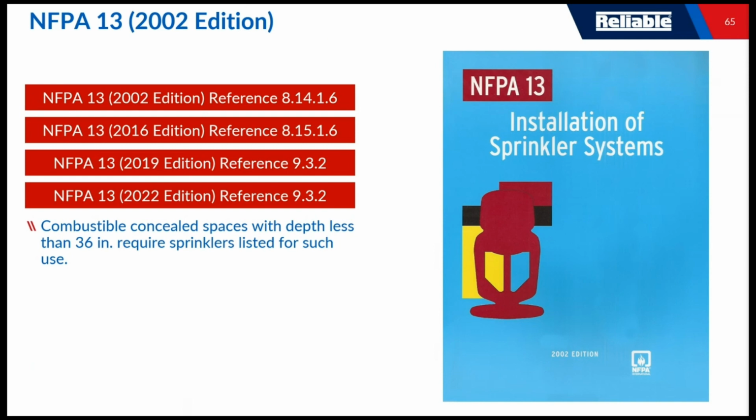Now, that 36 number there is actually the point where you can sort of get enough of that umbrella pattern from a standard spray sprinkler, and that will basically negate the requirement to use a special sprinkler. These sprinklers, however, have listings down to 60 inches. So that means you could actually continue to use them beyond the 36. And there are some benefits to using that, like using CPVC pipe, also having an extended coverage spray pattern versus that standard spray sprinkler that you'd use in that space.